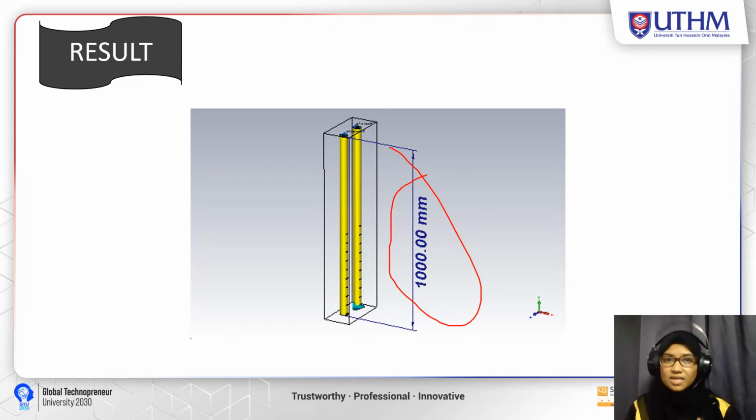Both cables are terminated with 50 ohm impedance. Cable 1 is set to be the active cable and cable 2 is set to be the passive cable. The voltage monitor is placed at the second cable because it is passive, to get the induced voltage.